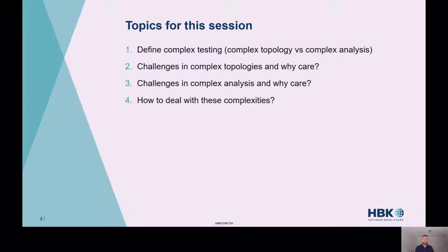When we talk about a complex system, we talk about how to handle the testing of drives with higher voltages, like for example over 1 kilovolt, more than 3 phases, or multiple motors and generators in one setup, which is a common sight in the marine industry. When we talk about complex analysis, we talk about tasks like NVH, noise vibration harshness, EQ0, space vector for complex calibration tasks, torque ripple, back EMF, dynamic power measurements, and correlating vibration and electric drive test data. Last but not least, we will look into how we can deal with these complexities.